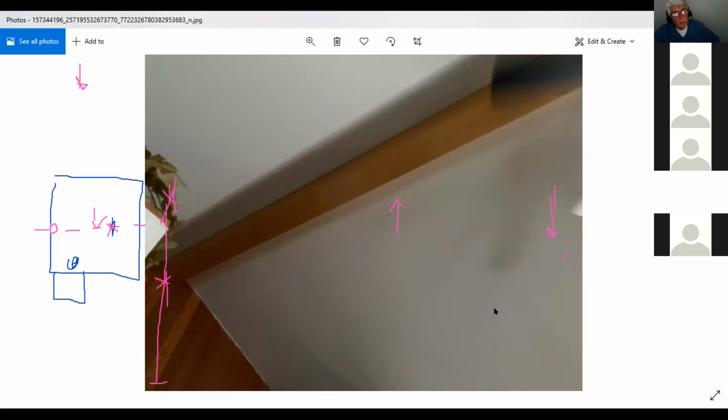You go to the top and you have to see how the loads are coming down into the structure. Okay, the load path. So for example, if I'm looking at a plan view of the roof, here's my beam, so I understand that all the loads are being supported by this beam. Now, is there a column only here or here? Or is there also a column here? That has to be determined, understand?